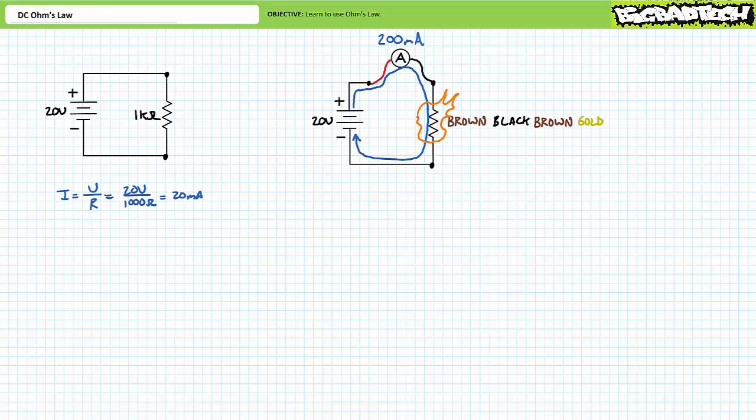The answer is right in front of you if you know where to look. There's really only three elements in this simple circuit: the voltage source, the ammeter, and the resistor, so it's obviously one of these that is at fault. Let's say a quick check of the voltage source with your voltmeter indicates the source really is at 20 volts. What's the problem? It's your lab partner. I warned you about this, didn't I?